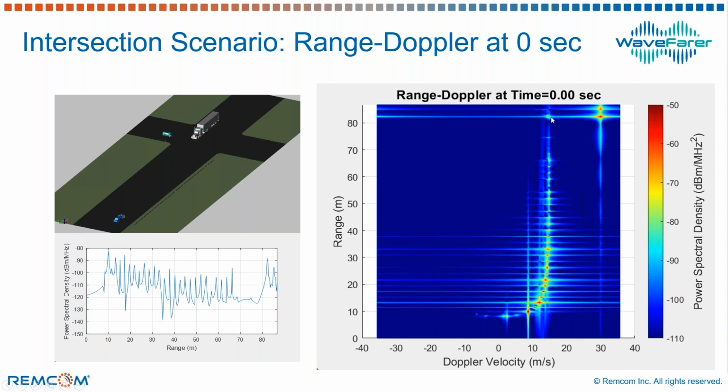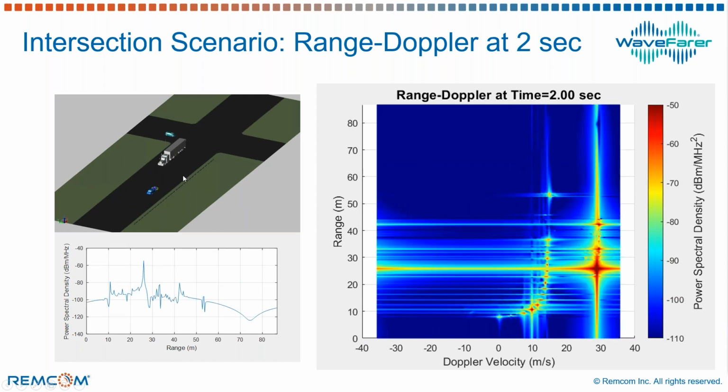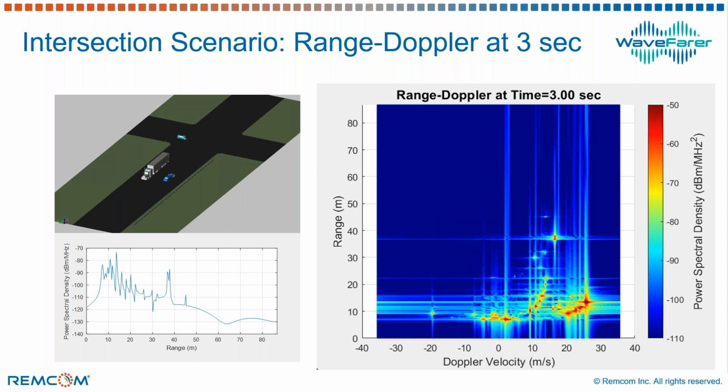When we do the Doppler processing, we pick up this scattering plot. The range-Doppler plot here shows the truck over here. At the moment, the car is stationary, and this is most likely the scattering coming back from the vehicle at the intersection. As the radar advances, the truck is getting closer. Of course, we see some of those guardrails approaching and then passing and shifting down in Doppler as they pass. The truck is now again getting closer. Its return is stronger. We still have the car stopped over here at the stop sign, although it's partly obscured by the passing truck.